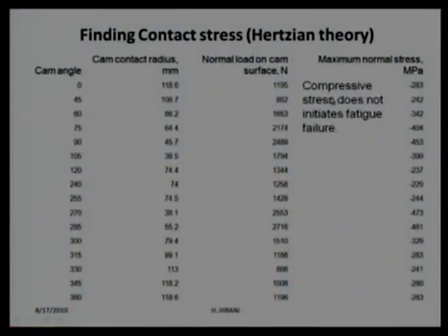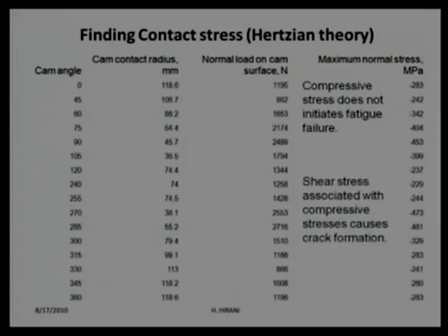Now, as I mentioned earlier, the compressive stress will not initiate the fatigue process, but the shear stresses associated with the compressive stresses cause the crack formation. Once the crack is formed, after repetitive loading we load, unload, close the crack, open the crack, close the crack, open the crack, and it will enlarge slowly and finally fracture will occur, or finally a pit formation will occur. And if sliding is introduced, pit formation will be much earlier.